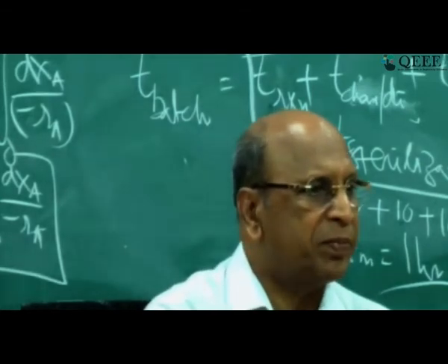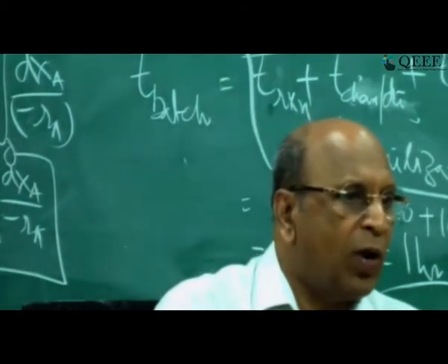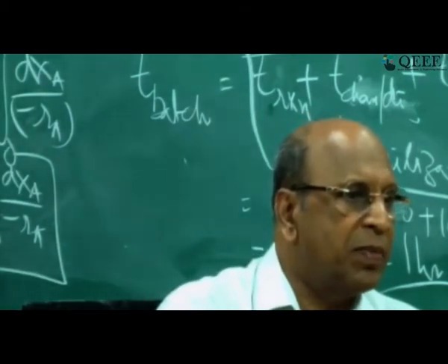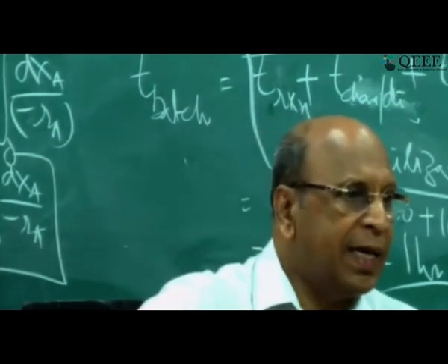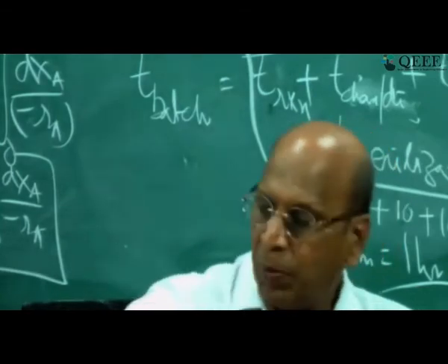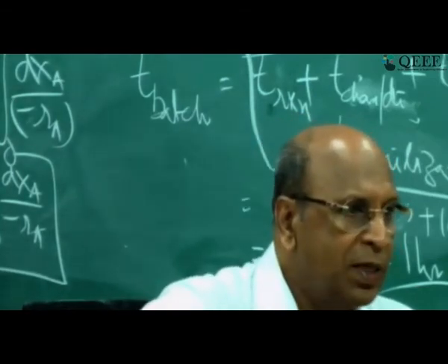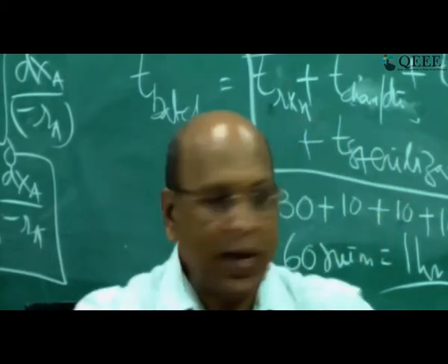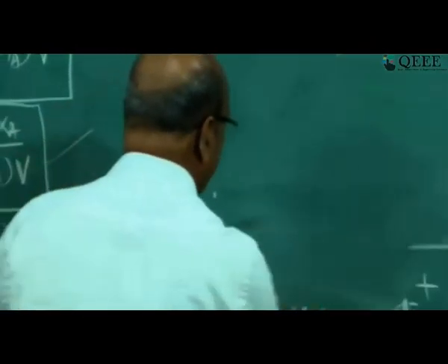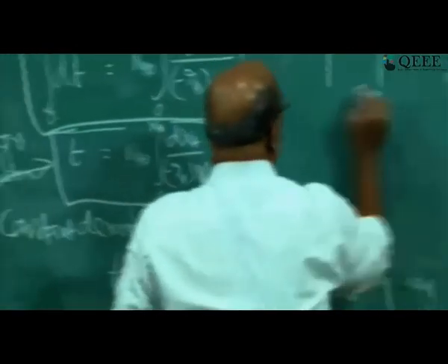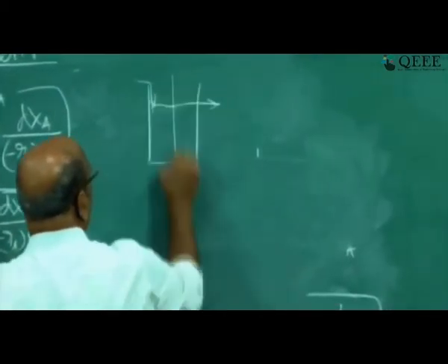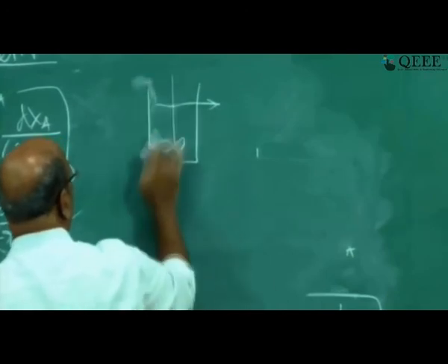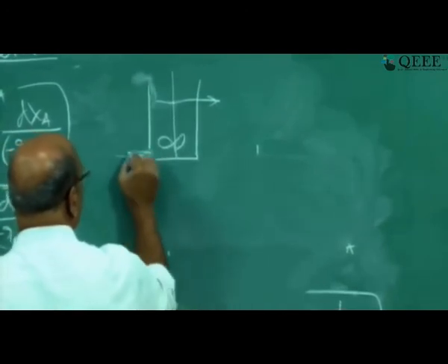That is definite. Okay. Is there any way to avoid or overcome bypass? Yes, by properly placing the inlet and outlet. We talked about bypass particularly in mixed flow reactors. One way to avoid bypass in mixed flow: normally we introduce the feed at the top and then take it out. So with stirring, now don't introduce it there, but introduce it here, and this is the overflow.